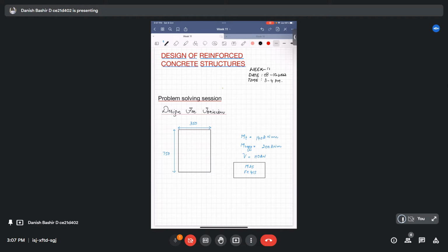From the equivalent shear force, we will deduce the equivalent shear stress, which we will use for designing the shear and torsional reinforcement, because that will tell us whether the stirrup design is governed by shear or by torsion. And the hogging moment will be used in reducing the equivalent bending moments for the design of the flexural reinforcement.